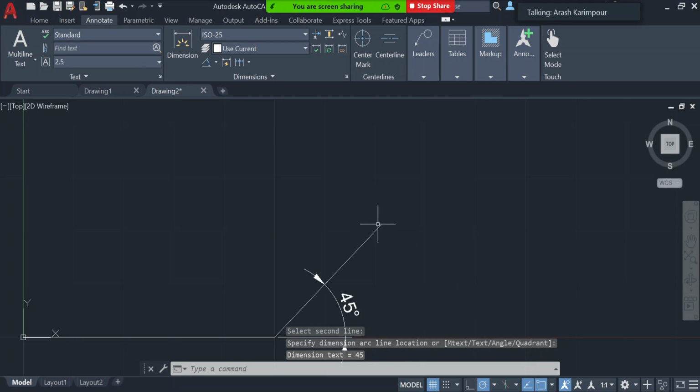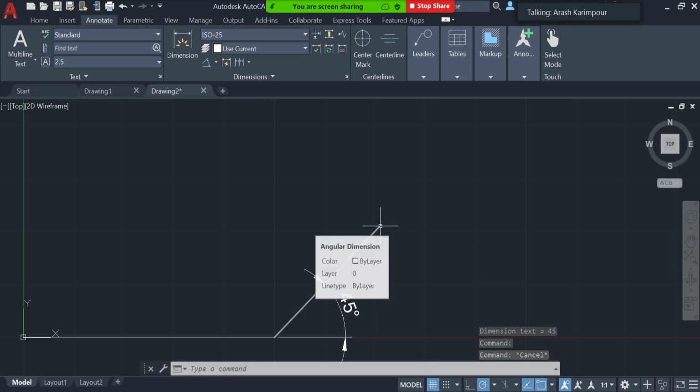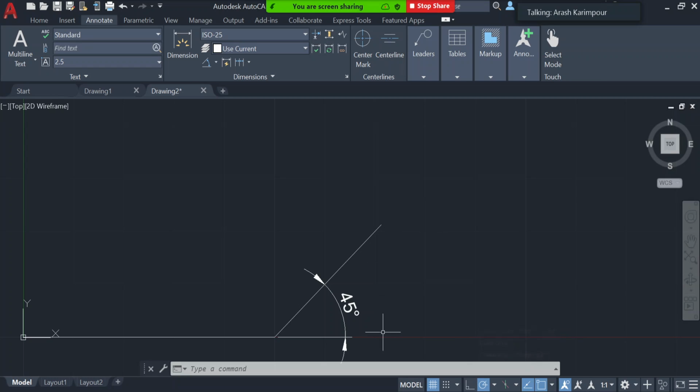Now assume I want to draw the line from the end of that, with 15 degrees with respect to this one. So one way of doing that is, I know this line is 45 degrees with respect to the horizon. The next one is 15 degrees with respect to that, so the next line is going to have the angle of 60 degrees with respect to the horizon.